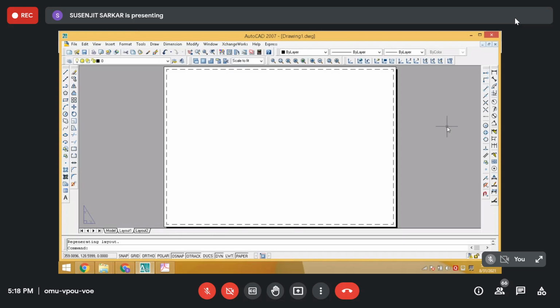And if you want to see the whole drawing, you put all the layers one above another to see the complete picture of your drawing, right? The advantage is that if you want to change a particular type of line or its properties, you can just change the layer property and everything will be changed. You don't have to go deeper into the drawing or change all the different lines, right? So these are the advantages.